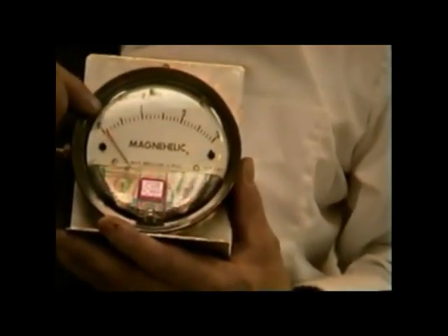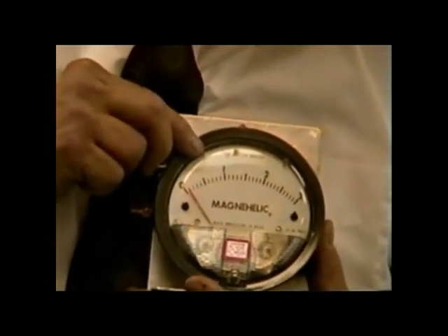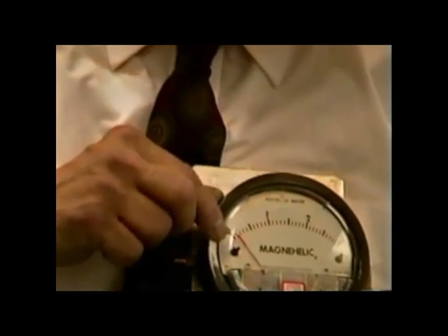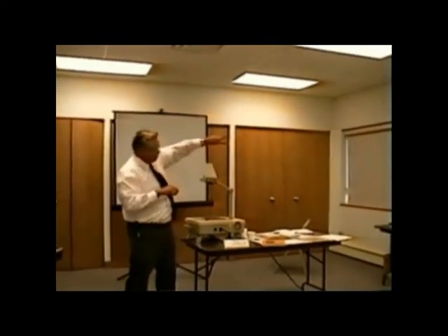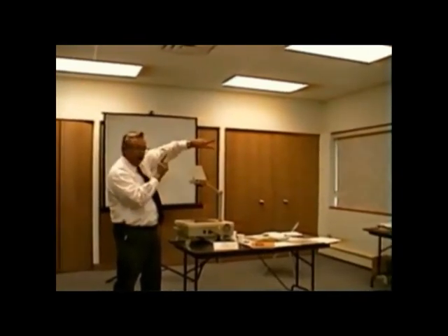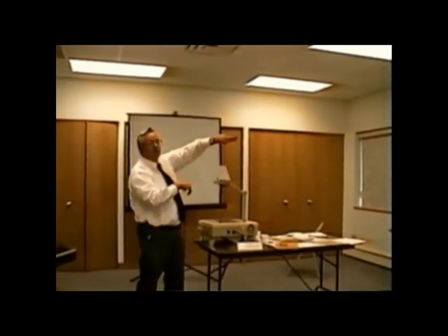0.1, 0.2, 0.3, 0.4, 0.5, 0.6, 0.7, 0.8, 0.9, 1 inch. Okay? So you get increments in 1/10 of an inch. So we can read 0.3, 0.4, 0.5, right? As the inducer is on and we watch it and the switch is open, we read 0.1, 0.2, negative 0.3, 0.4, and it closes. 0.5, 0.6, 0.7, and it could go all the way up to 1 inch above it.